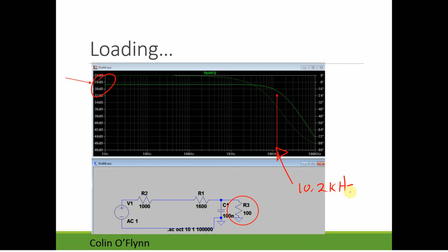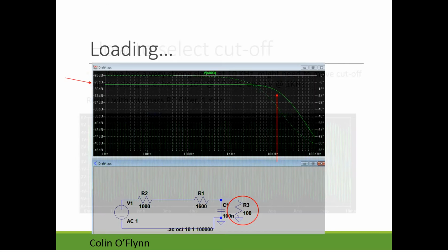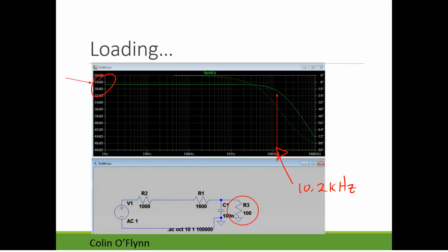So we've drastically changed the low pass filter frequency response. Those are things you have to be aware of, and you should either simulate your circuit or test it. And again, you can test it using the signal generator in the lab with the oscilloscope to plot the response.